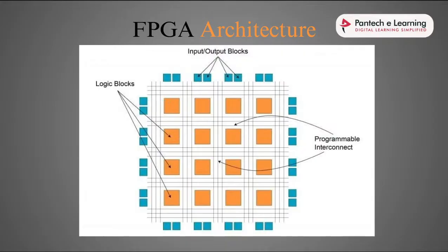Our code, like a Verilog code, a text design code, will be converted into a gate level netlist, and then CMOS transistors. That particular tool, like if you are using the Xilinx tool, will automatically assign that. So this particular CLB is only for the FA, the full adder. This CLB will do the full adder operation continuously. Based on our inputs it will perform the operation, and you will get the output on the IO pins. This is the main working.